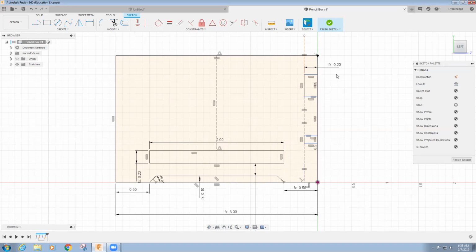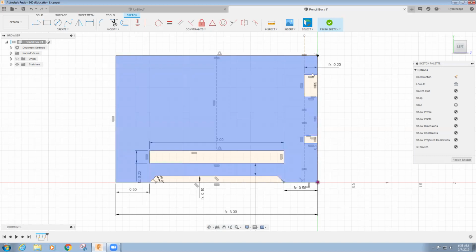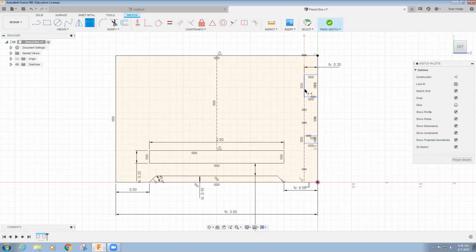I'm going to make the tabs true squares, so I'll give it a value of T, and I may want to go back and change that later. So I won't make it use an equal constraint to the side value here. Let's see. I need to use the equal constraint to make those 2 equal.